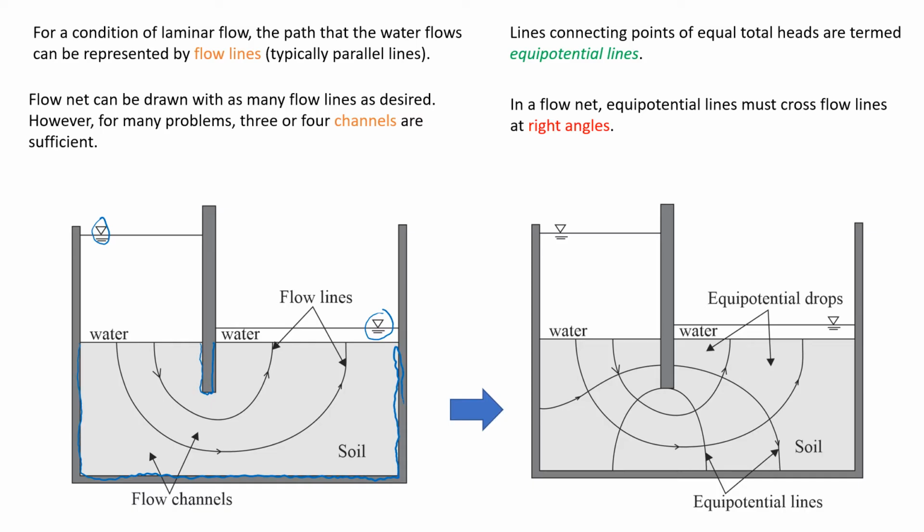Now we're going to draw additional flow lines, and we would like to draw them as parallel as possible, as shown here. You see this is already one flow line drawn here, and this is the second one. What is important is to keep about the same distance between flow lines. If we measure this distance, it should be equal or similar to this distance and to this distance. This is one of the major rules of drawing flow lines. And the space between flow lines we call a channel. So in this case we have one channel here.